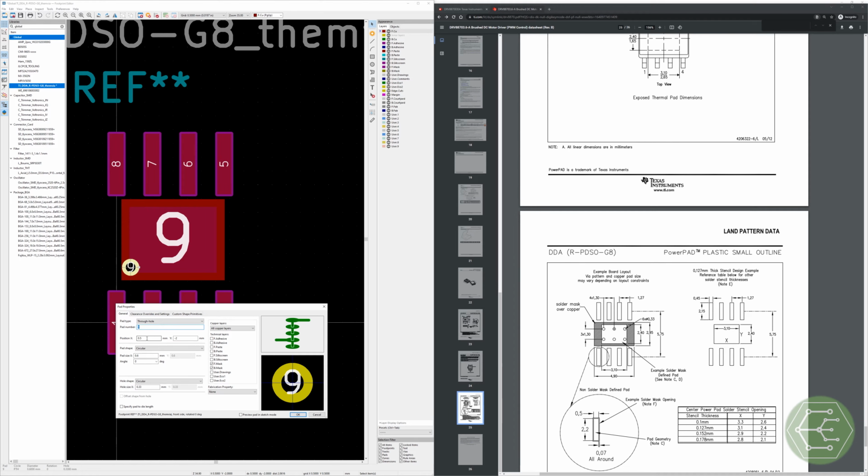Position X. And then we need to subtract 1 hole spacing. So we'll take off 1.3. That should leave us with 0.605 in the X direction. And in the Y direction, okay, so we want to go to the center of the part. So we will take 5.75 divided by 2.